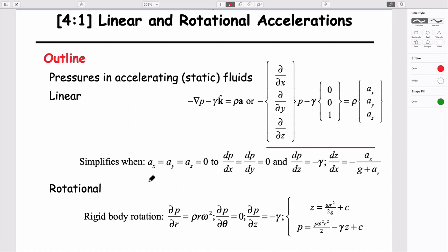We've always so far assumed that accelerations are zero. This expression that we had before is a longer expression, and if I divide it up about this point here and paraphrase it, this is basically what it is. These two components on the left, dP/dx or dy, and the unit weights of the fluid are forces in the system. And these are parts that are due to acceleration.